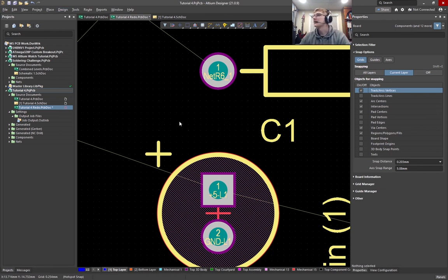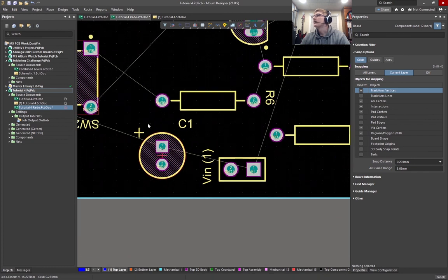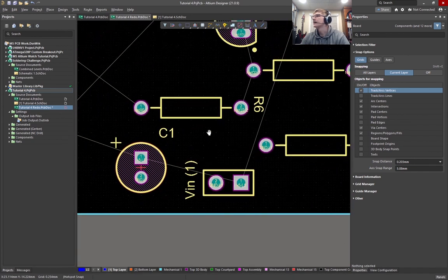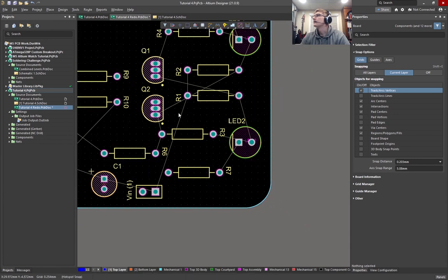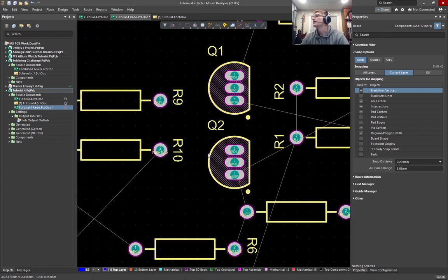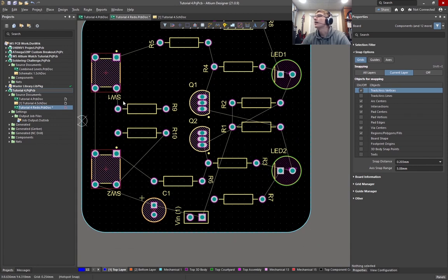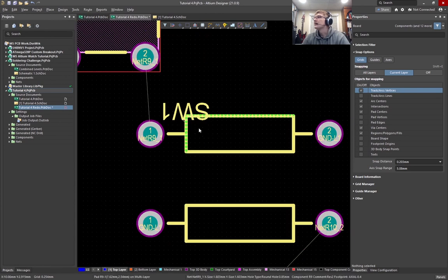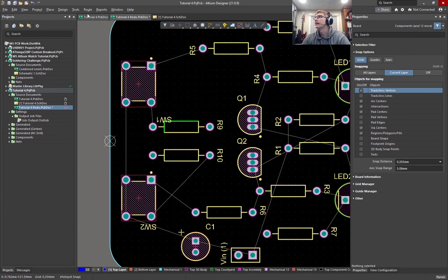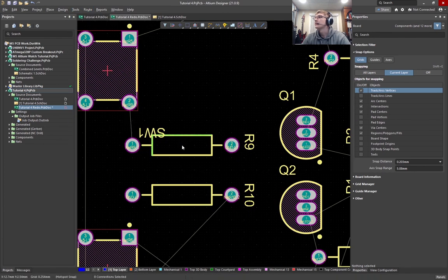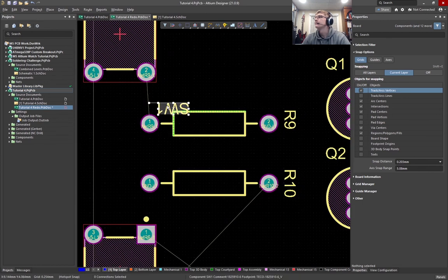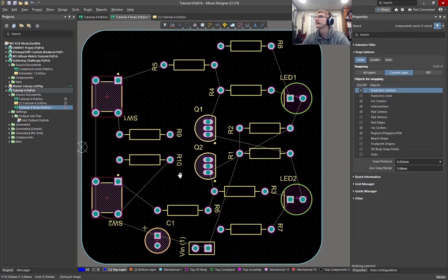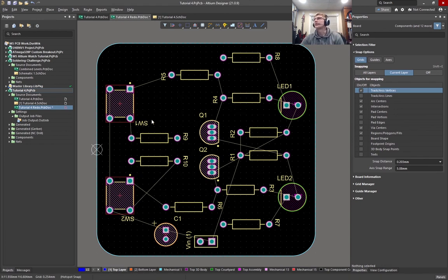So I'm going to move this, and you can see I just cleared up that error just by moving that a little bit to the side. So now I don't have that error. By the way, if there are errors in your board that you know about and want to ignore for the time being, for example, let's say I have this here, there's an error, and I know I'm going to clear it up later. There's just a couple things I need to do first. Tools, reset error markers. I'll get rid of those for now, but if I ever go to move this later, they'll come back, right? So it's like a temporary way to just disable those very annoying green dots, which might be distracting you while you're trying to get something else done.